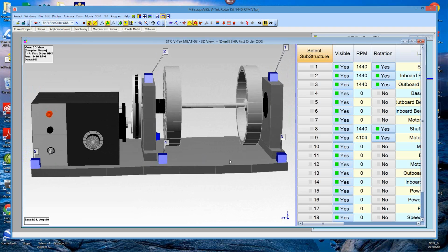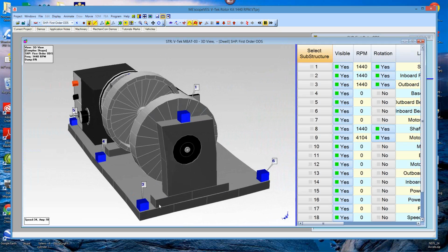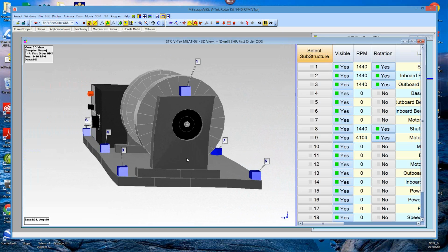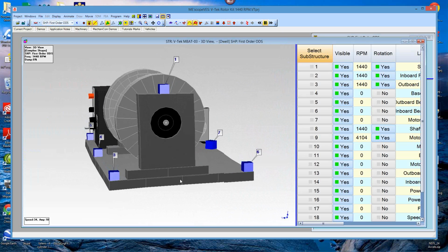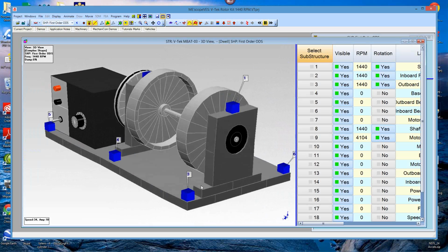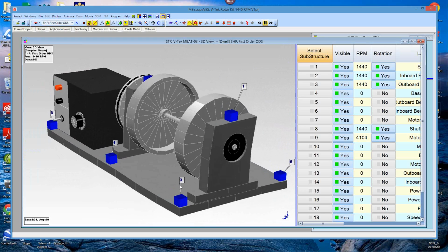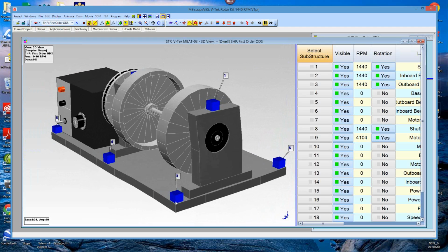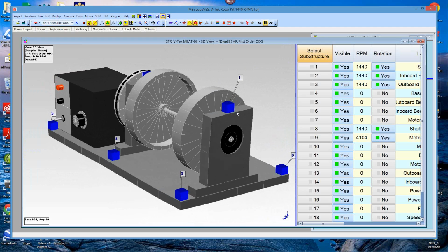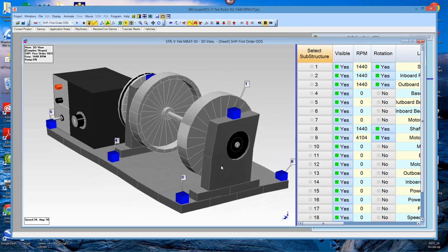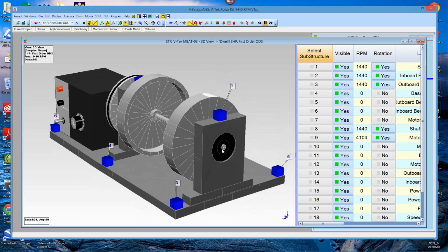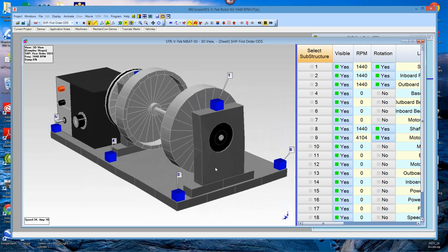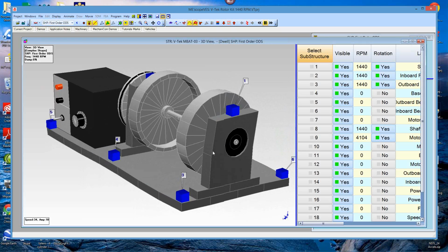However, we want the bottom of the bearing block to follow the accelerometers at the base plate. You can see it's a little bit unrealistic here, but the way I set that up was to do some interpolation, first of all using all 3 accelerometers, and then go back and make the center of the shaft, the bearing itself, and the cutout follow the top accelerometer.